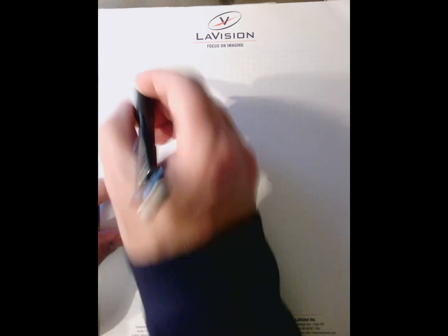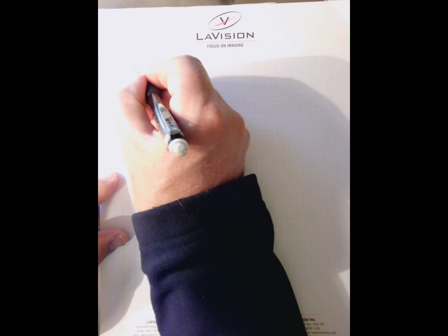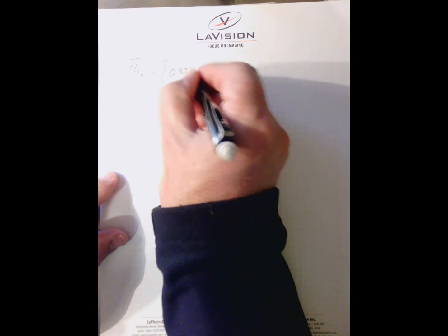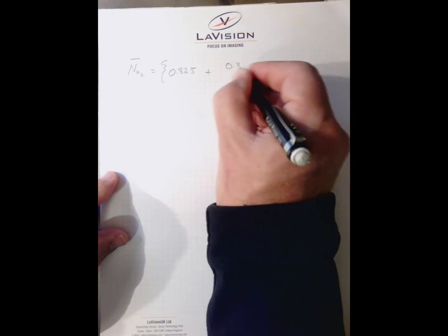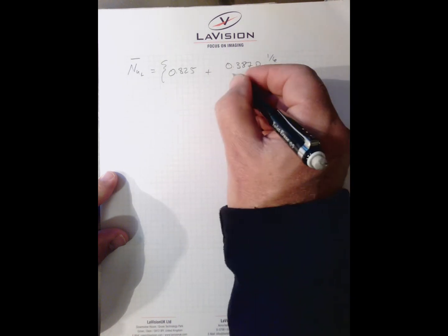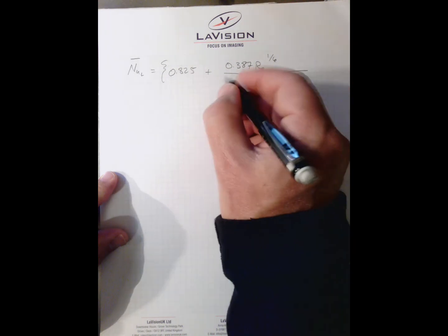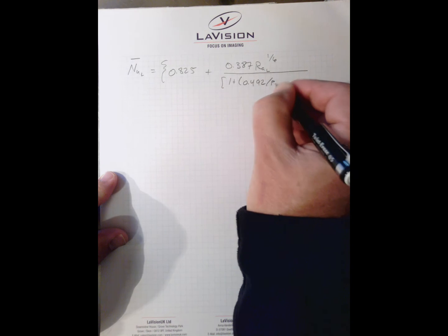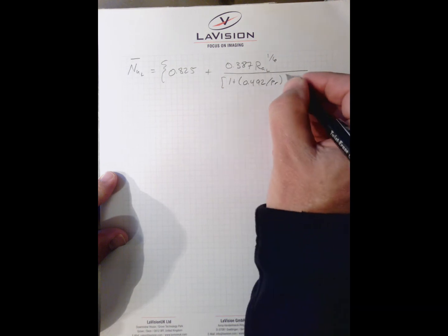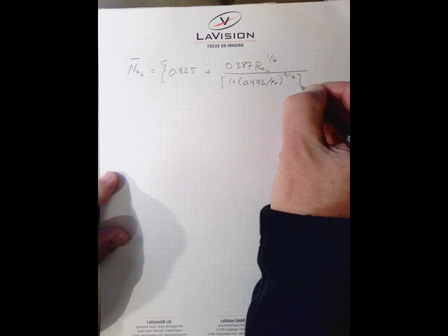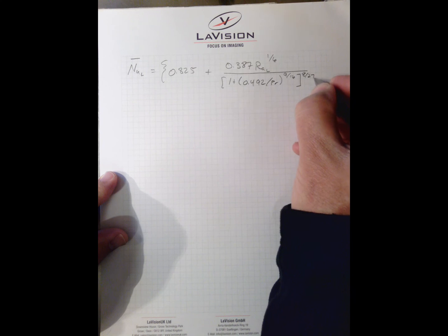So in that case, my Nusselt number for that case, which is based on an L length scale, is 0.825 plus 0.387 Rayleigh based on length to the 1/6, over 1 plus 0.492 over Prandtl number to the 9/16, to the 8/27ths, and the entire mess squared.